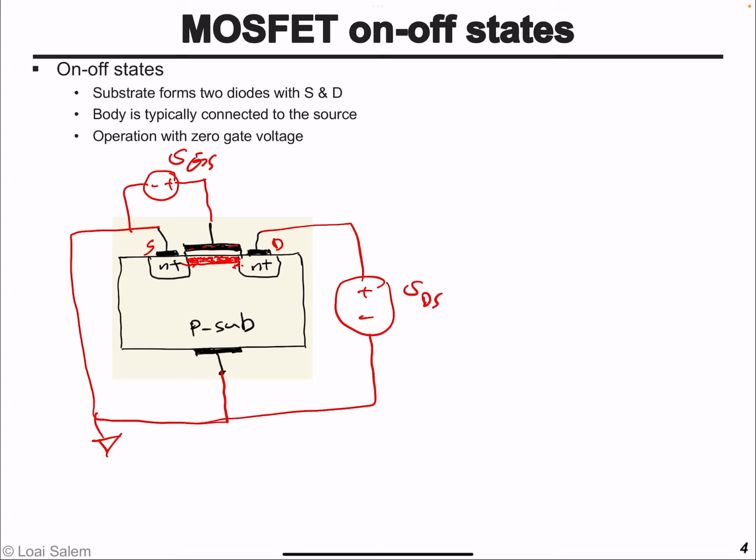source and drain. And the gate to source voltage value that causes enough electrons in that channel so that the channel connects the source to the drain, or behaves as a short circuit between the source and the drain, is called the threshold voltage. So again, we can say that when the gate to source voltage is larger than the threshold voltage, the switch is on, and the transistor establishes a conducting channel between the source and drain. When the gate to source voltage is less than the threshold voltage, there aren't enough electrons to establish a conducting channel, so the transistor is in the off state.